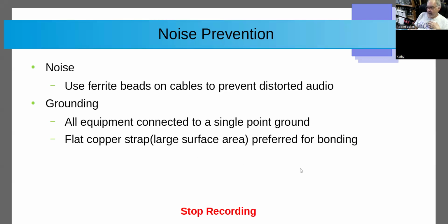Also, when you connect to ground rods, any of these things where you're doing it for lightning protection, you want to make sure that you're using either a welded connection or a compression connection. You never use solder. Solder would instantly vaporize when you get a few thousand amps running through it.